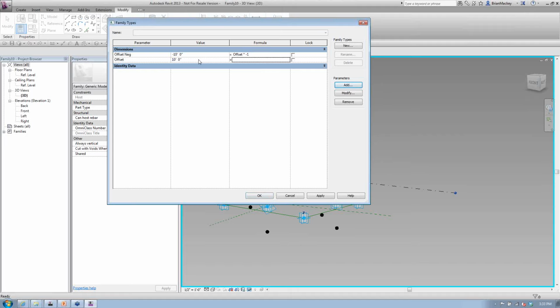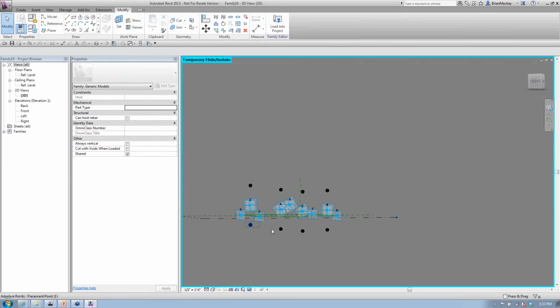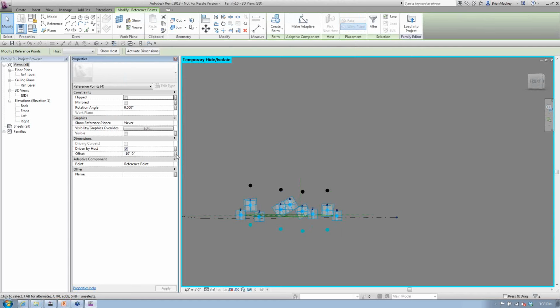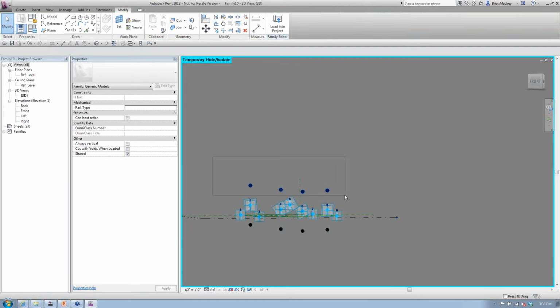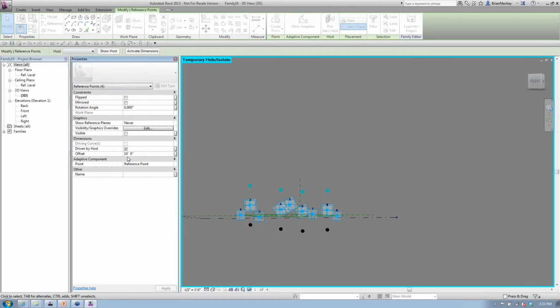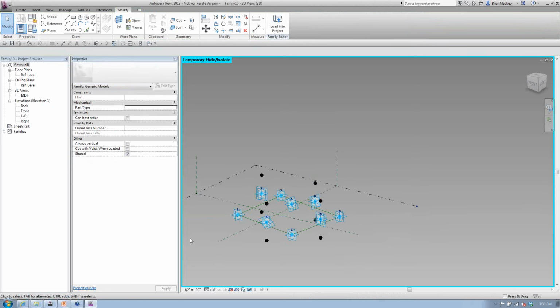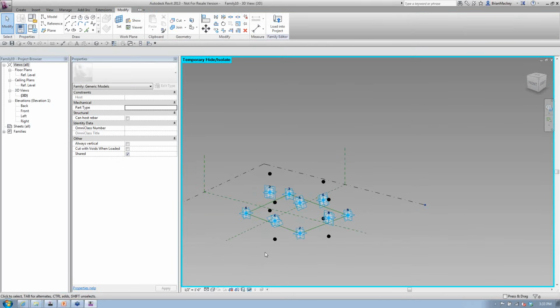Let's actually go back and change that to be 10. So now with that said, I'm going to grab all these points that are down low and set those to the offset negative, and grab these points up high and set them to the offset. I really want to get these all set up, being tall, doing what I want them to do. There are multiple different ways to do what I'm doing with this deformation panel. You get a deformation at the center, at the ends.